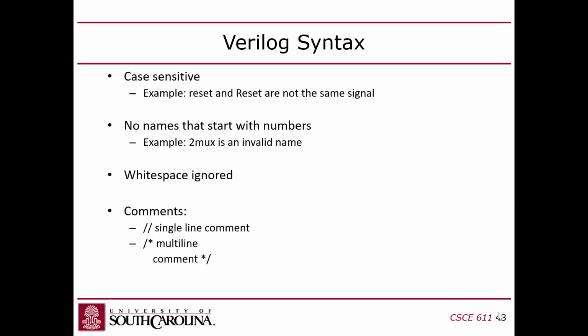Okay, so a couple quick things. Verilog is case sensitive, like Java and C, so you guys are used to that. You might say every language is case sensitive, right? No, VHDL is not. VHDL is case insensitive. That's why we bring this up. Names can't start with numbers, white space is ignored, and comments are the same format, luckily, as Java and C. Same comments. White space is ignored, though.